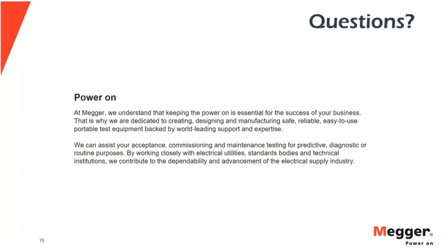So by doing power factor testing, narrowband DFR, full DFR, by doing various oil tests, these are all to increase our knowledge of insulation health and how suitable the materials are to continue to do a good job of supporting an electric field and not, well, worst case, dielectric failure is synonymous with failure of the asset.